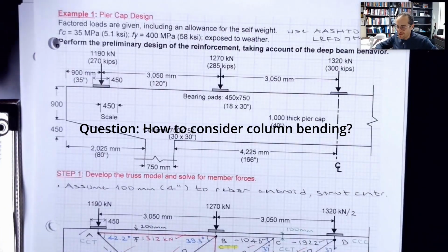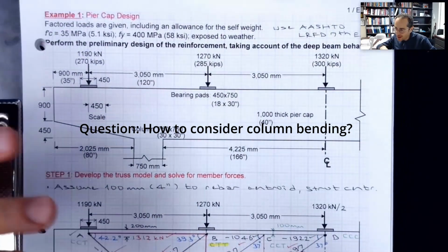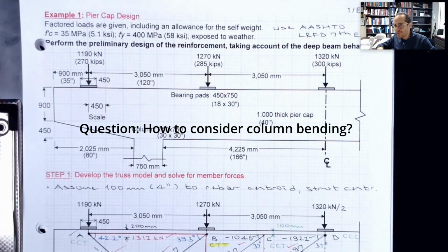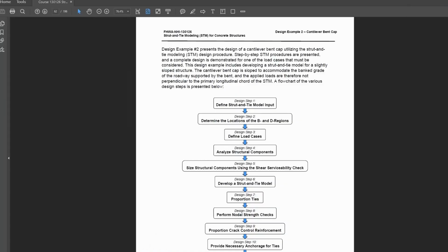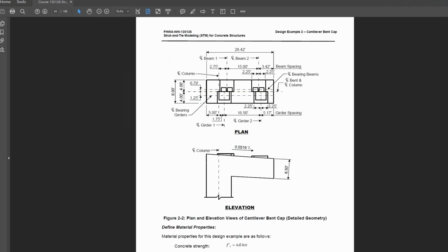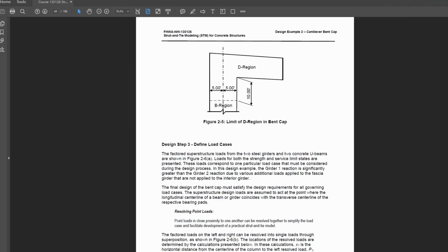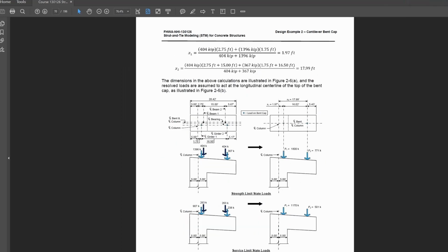That is definitely advanced. I mean, if you go into a bending situation with strut-and-tie, it is going to be rather involved. I can show you some sample solutions. So in this example, it is a bend which is cantilever, as you said. This is intended to create moment, so there is significant bending moment which you cannot neglect. The general issue is similar to your question.